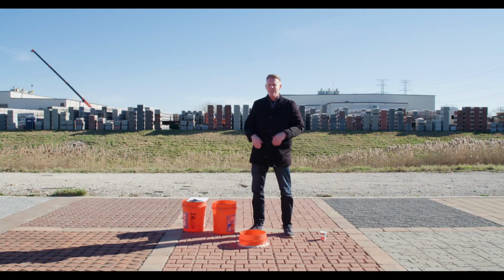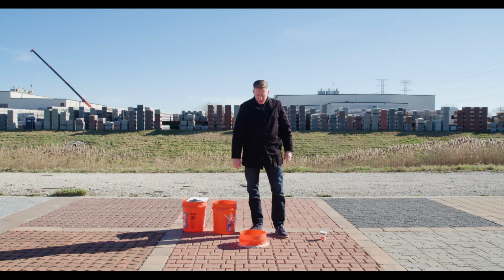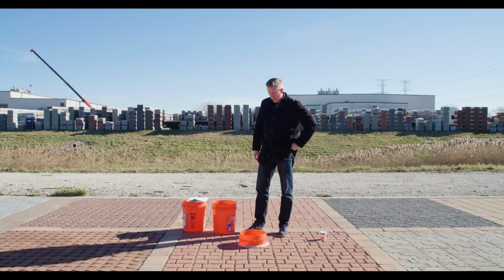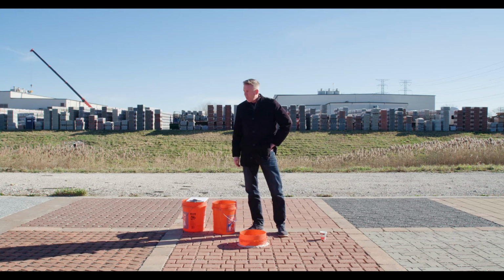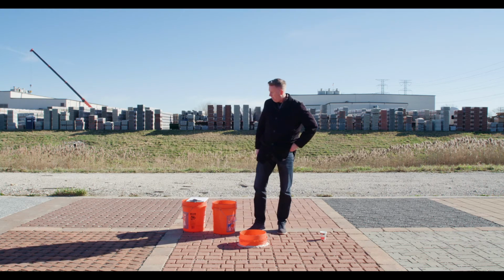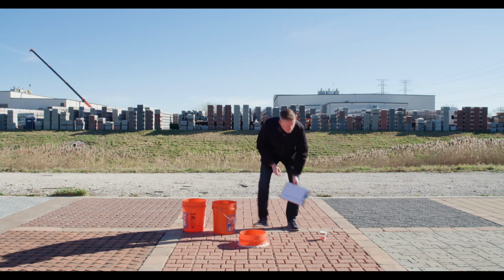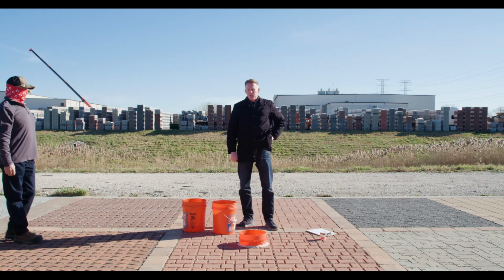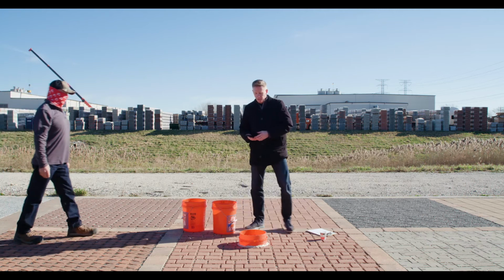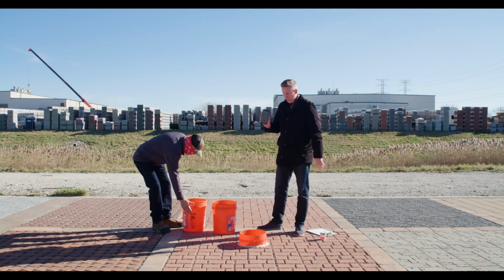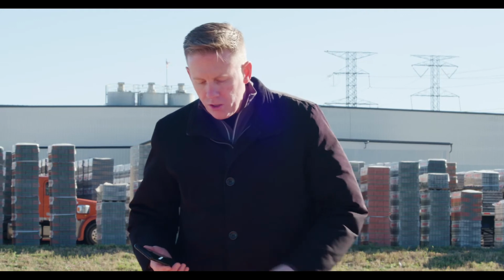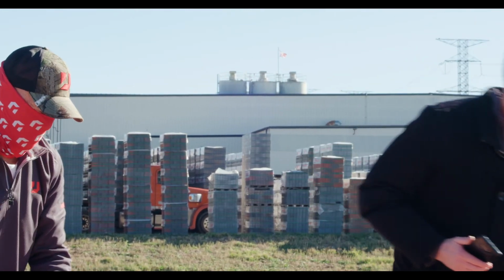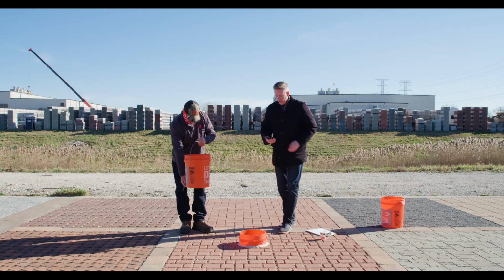All right, now that we've sealed up around the outside of the ring, we can start doing our pour test. Now we're going to start off with 8 pounds of water. We're going to pour this into the ring, and we're going to time it to see how long it takes for that 8 pounds of water to infiltrate. So pull up our timer here, and as soon as the water hits the surface of the paver, then we're going to start to time this draining.